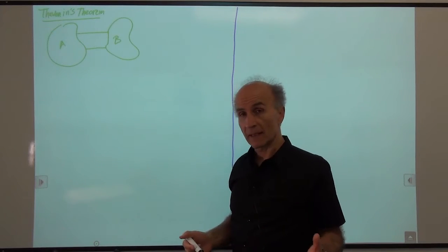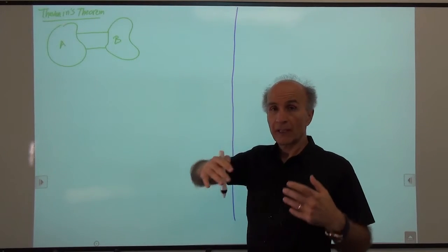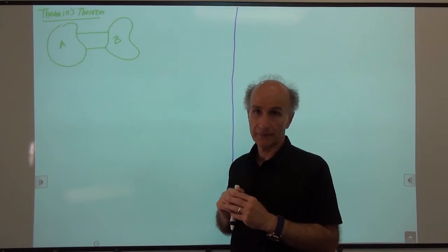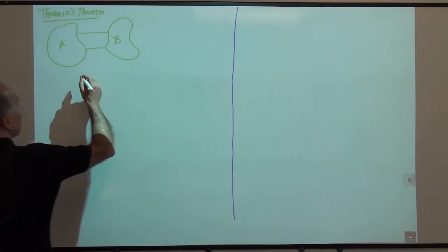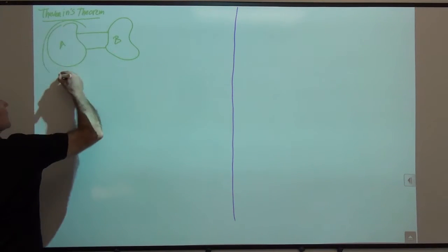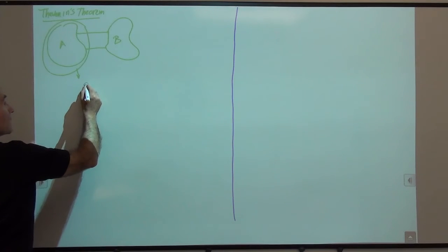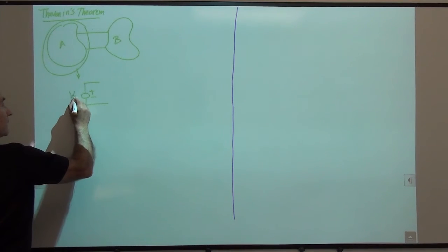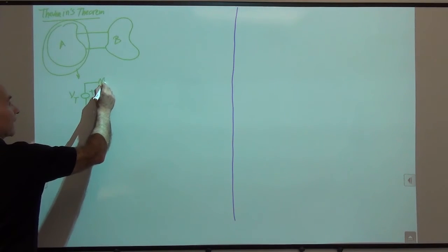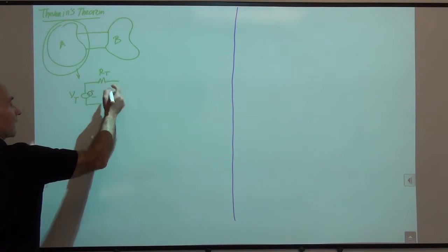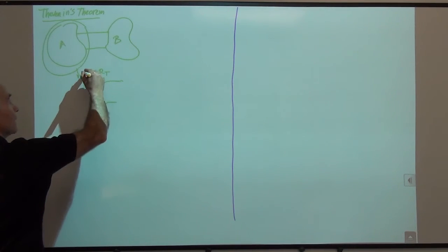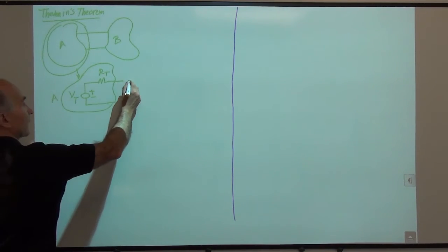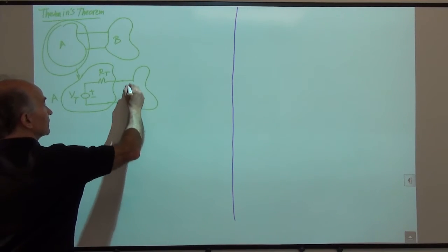Okay, so Thevenin says that for each of these, you can create a much simpler equivalent circuit. So Thevenin says that I can replace this whole thing with a simple model. So in fact, it will be like this. It will be a voltage source, which we call VT, T for Thevenin, and a resistor we call RT, Thevenin resistance. And this is the entire A. And then if you want to connect it to B, sure, we connect it to B.